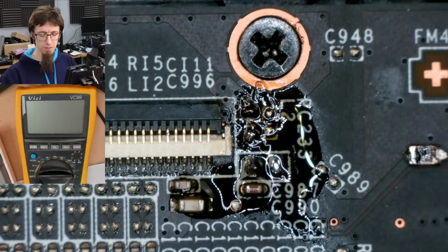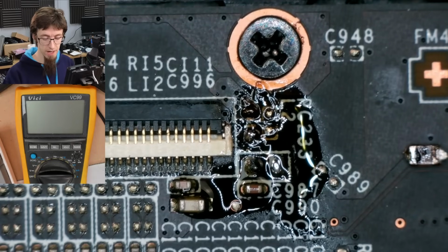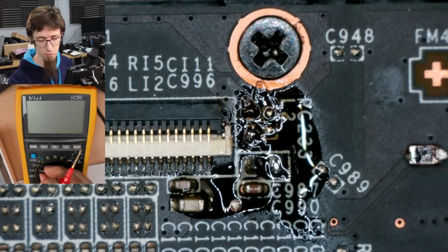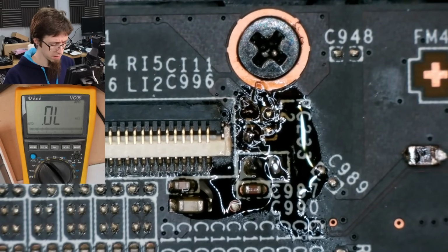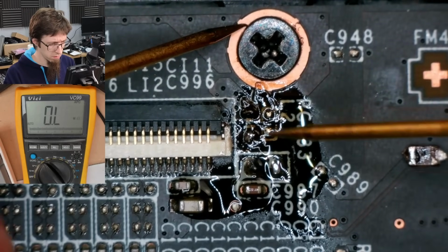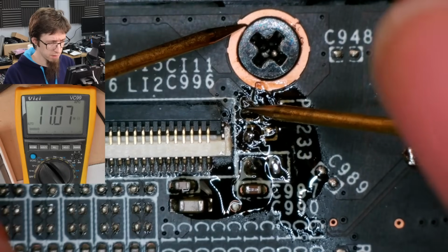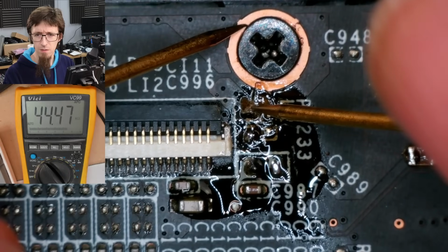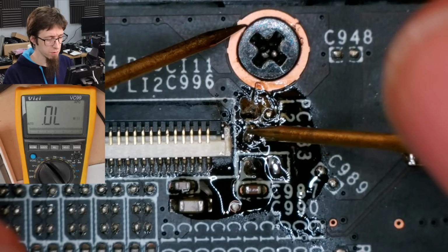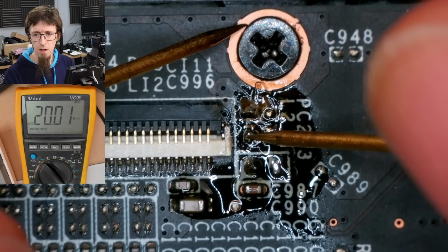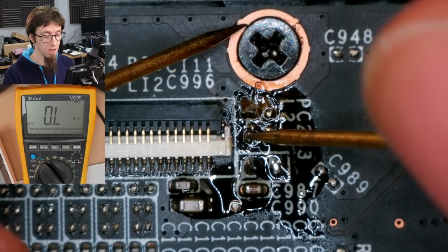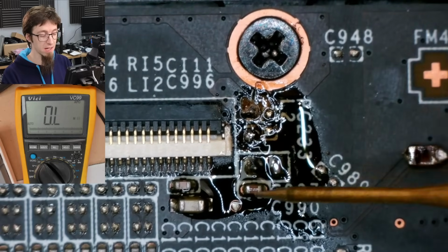Firstly, we're going to do a little bit of a spot check with the multimeter again and just see if our short has disappeared. Now that capacitor is off the board, we should find that we're no longer shorted. So, black probe on the screw hole. So the input side wasn't shorted in the first place, but we'll just verify that. Yep, lots of resistance there. And now the output side. Yeah, that's also no longer shorted. We're getting mega ohms, out of range there, because there's basically nothing else on that rail except that capacitor now.